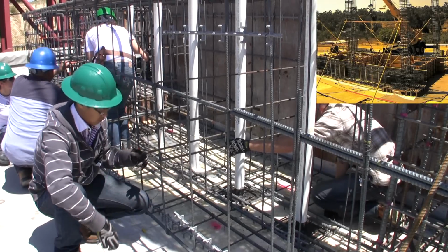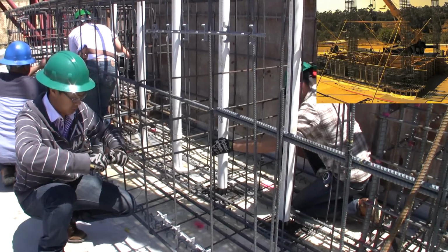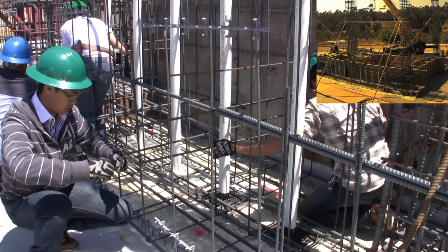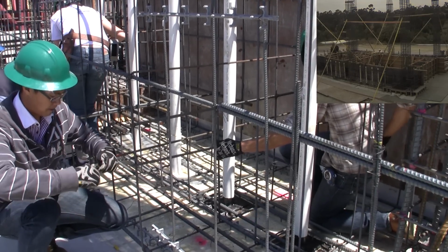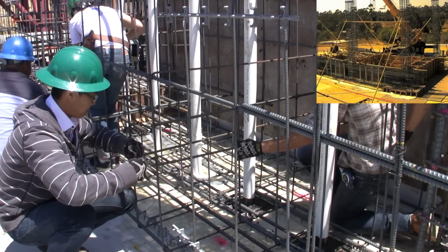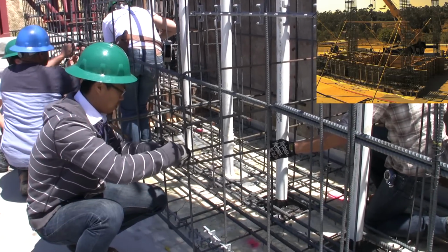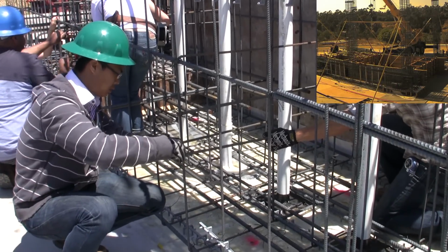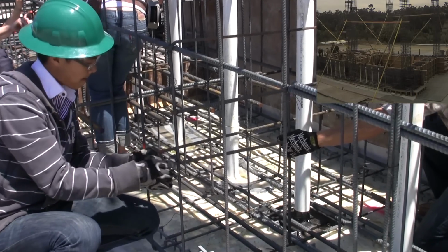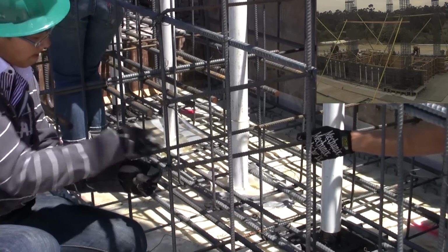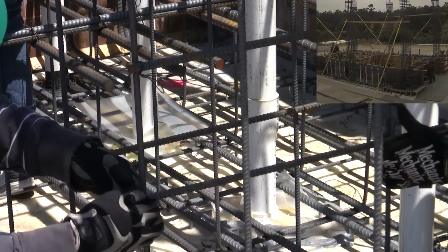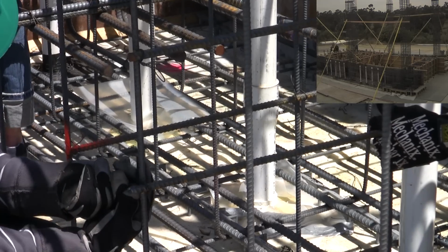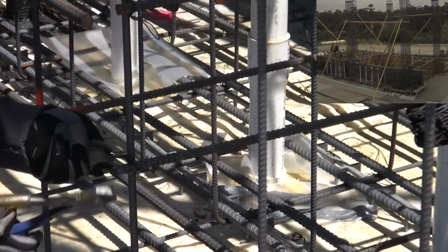Small diameter rebar are often bent or cut manually with a hickey, whereas larger rebar must be modified using a hydraulic machine. The rebar typically have ribs on them to facilitate a strong mechanical interlock with the concrete. Once the rebar are sized and shaped according to the specifications, they are then connected to each other, typically using steel tie wire to form a three-dimensional rebar cage. Welding of rebar cages may also be used, however it is not common, and only ASTM A706 low alloy rebar is typically ready to weld.